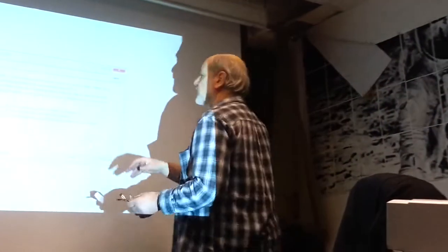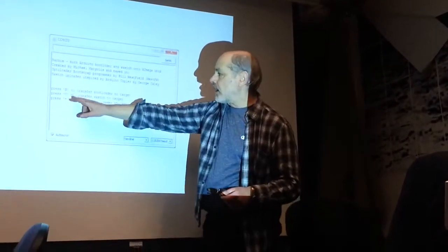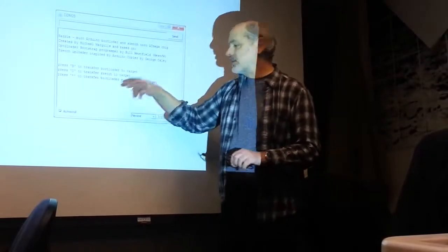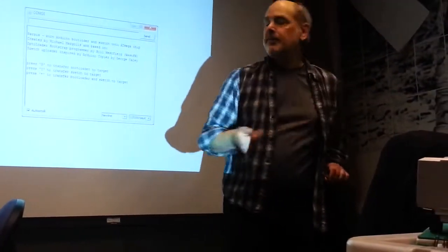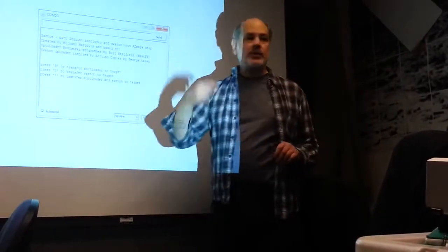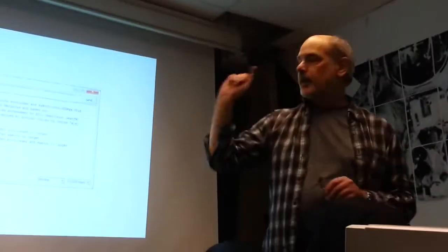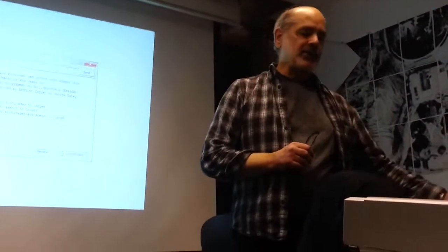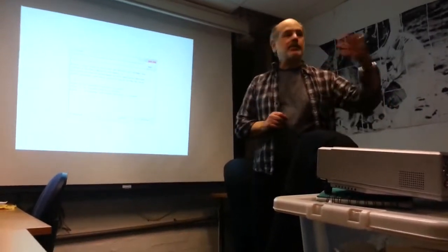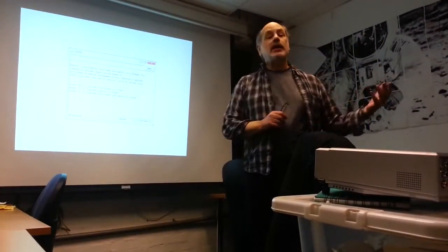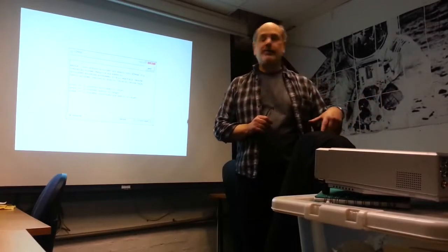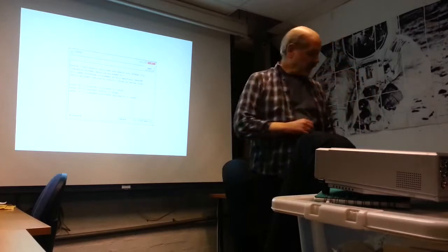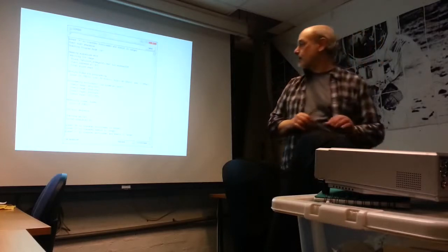So when you run it up, it offers you three options. Press B to burn the bootloader onto the target. Press U to just transfer or upload the test sketch, or press star to do both. So on a raw chip, you press star, it will then burn the bootloader, and then it will upload the test sketch. The test sketch is typically the blink LED sketch, so if it's worked, immediately after the upload's complete, the LED will start blinking. So it's successful. You're welcome to get that from me if you're interested.